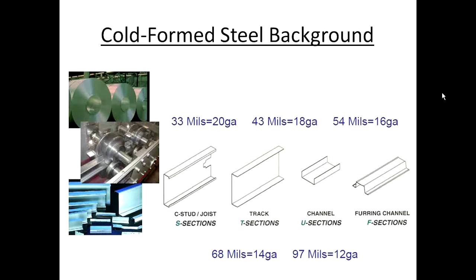And what you're looking at in that top slide are coils of steel that are being shipped into a steel stud manufacturer. That's the way they arrive. They come from the mill. They're pre-coated with corrosion-resistant material. Typically, the benchmark of performance is galvanization, so it's coated in zinc and galvanized, and it's slit into the widths of sizes it's needed for the individual profiles. We call that the blank width, and then mounted on a machine or the cold form machine to process the eventual shapes that we need.